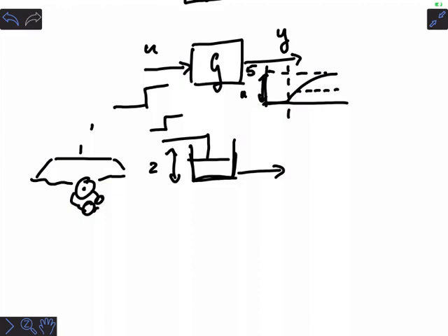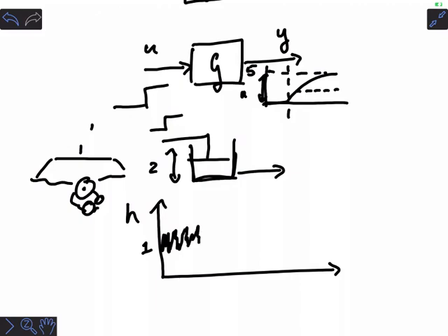So what's the solution? A lot of you are thinking, wait a minute, I have a very special solution here. I don't have to do a unit step, right? I can just do a small step. But then it becomes complicated. Let's say, again with our level here, that's level over time, and the level is hovering around 1 meter. And when I say hovering, I'm saying, as all real measurements do, there's some noise in the measurement signal. There's maybe mechanical noise in the tank itself. Maybe it's being mixed, so the level itself is not crystal clear, perfect. It's kind of moving around. There's electronic noise. There's all that kind of stuff.